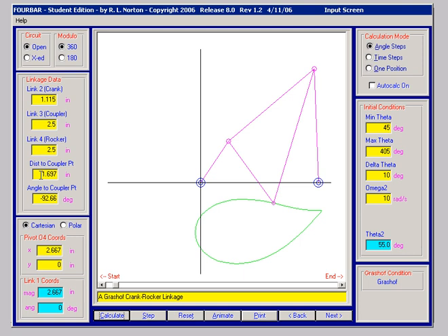So that's defined as being a distance 1.697 at an angle of minus 92.66 degrees from the left-hand end of link 3. In this particular case, more correctly, the end of link 3 that joins link 2, or instance center 2-3, another way to put that. So here's 1.697 inches at an angle of negative 92.66 degrees. That defines this coupler point.